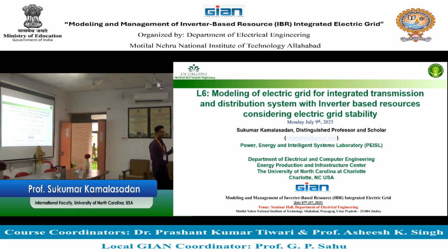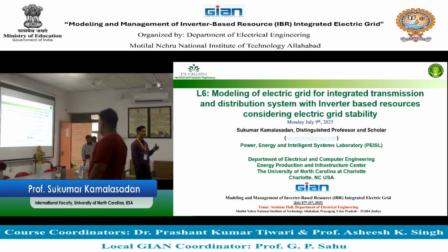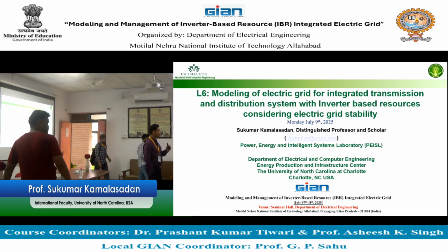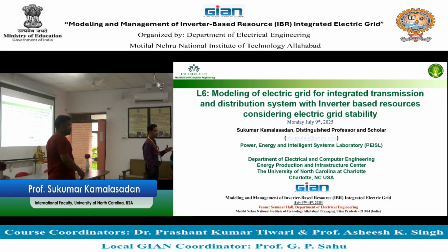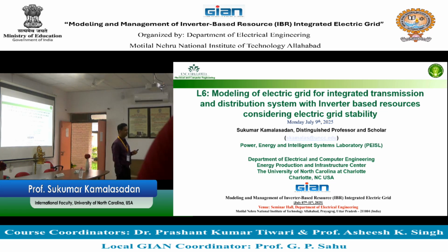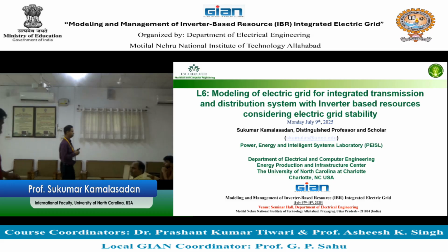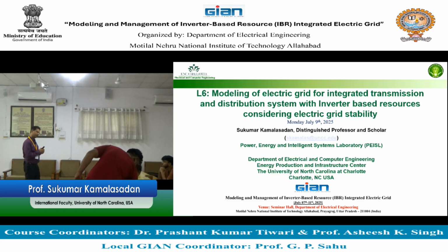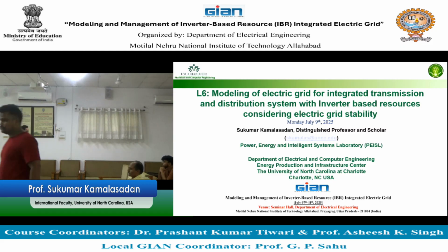And then we said, okay, this power flow model you can run in the form of snapshot. So you can run the power flow every 15 minutes, every 30 minutes in operation, right? Normally power flow is used for planning purposes, meaning you can use a power flow to design an electric grid. Where do you need to improve the voltage, right? What do you get from power flow? You get the voltages and angle of the voltages from power flow.